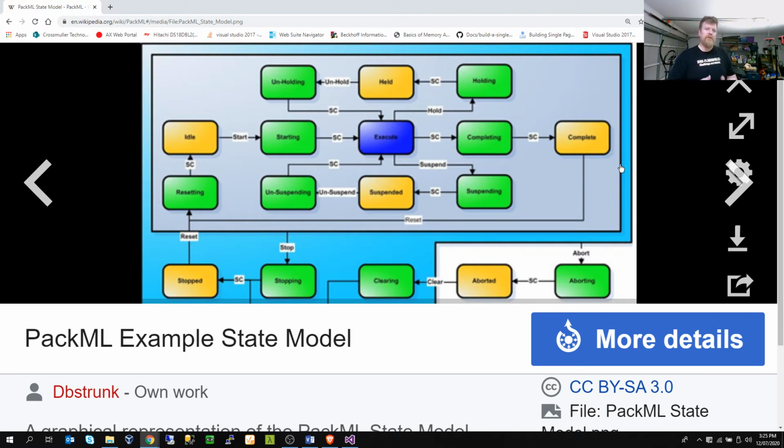There are numbers that represent different states. For example, if you've got a conveyor system and your conveyor system can't feed product in because there's nothing coming from the previous system, there's a range of state numbers that are pre-prescribed that most people who use these standards will be aware of, and starved for product because of blockage will have a number. Not all of the numbers are specified, so there are many hundreds in a range from 6,000 to 7,000, for example, that you can nominate your own for, but the first couple of dozen from that block will have pre-allocated meanings, and most of those meanings will cover most of your common use cases.